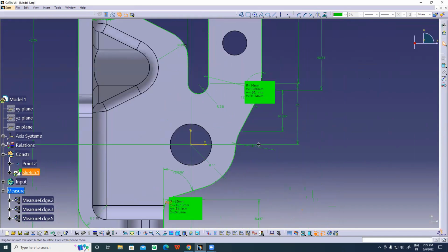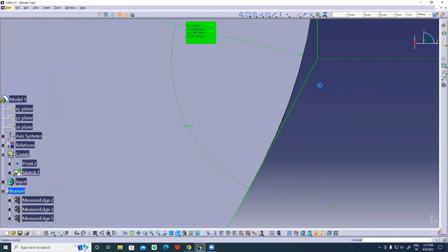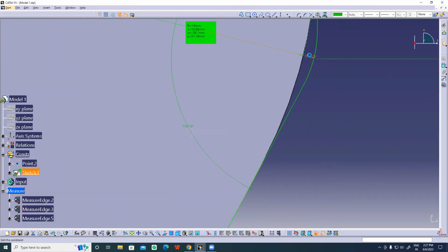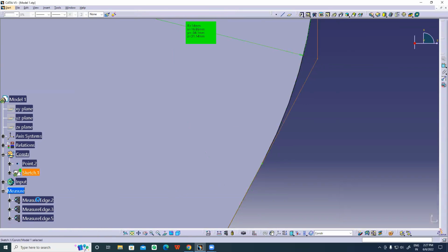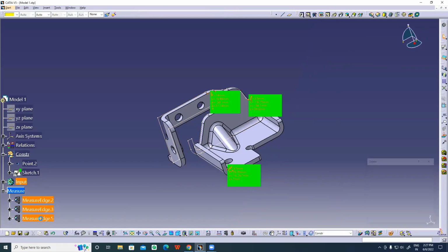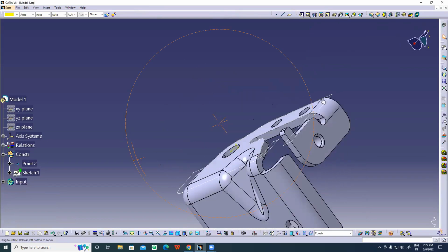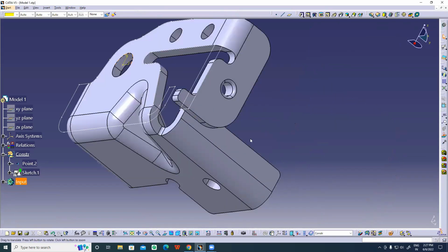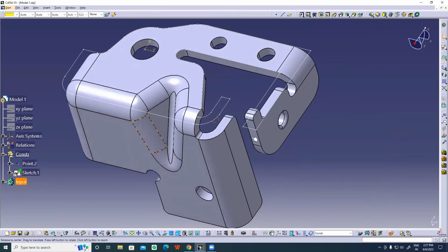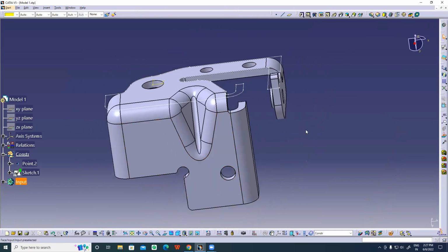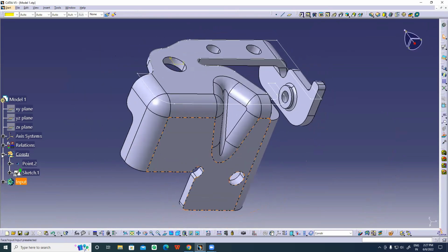Okay, and where else do we need to apply a fillet? This corner. This is an individual corner, we have to apply a fillet value as 14. I'll just apply it and change the value to 14, exit. So once after this, you don't want any measure, let's delete the measure. Clear, guys? Any questions in this? So you can see now we have created a sketch like this. Is anybody having questions in this? No, sir. No, sir. No, sir.